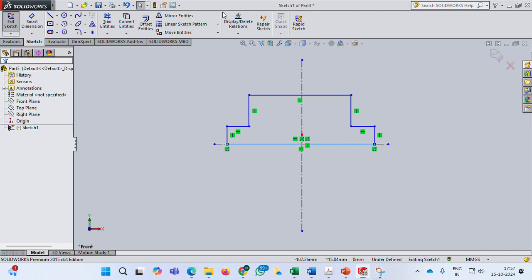Next, I am going to make this geometry symmetric, because whenever I specify a dimension, I want that dimension to be equally shared on both sides, towards left and towards right. If you are not making this geometry symmetric, in later cases when adding additional features, it will be very difficult to perform the operations.